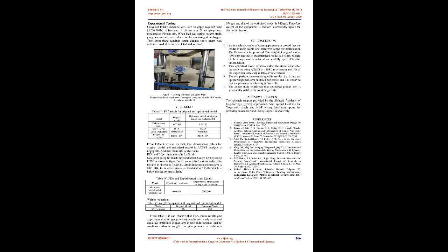3. The comparison between the fatigue life results of the existing and optimized Pitman Arm has been performed, and it is observed that the Pitman Arm has infinite life. 4. The above study confirmed that the optimized Pitman Arm is structurally stable with good fatigue life.